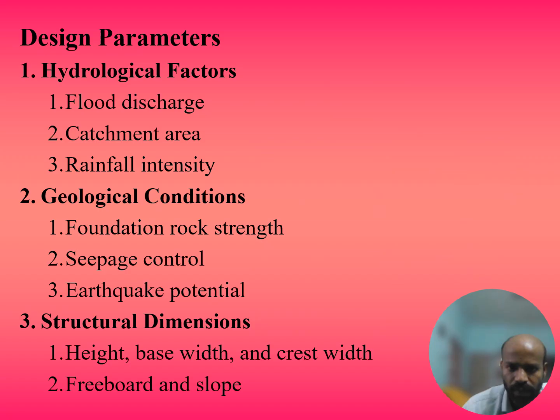When we design a dam, 6 key parameters are to be kept in mind, and they are hydrological factors, geological conditions, structural dimensions, material properties, reservoir capacity, and spillway design. Under hydrological factors, importance is given to flood discharge, catchment area, and rainfall intensity.